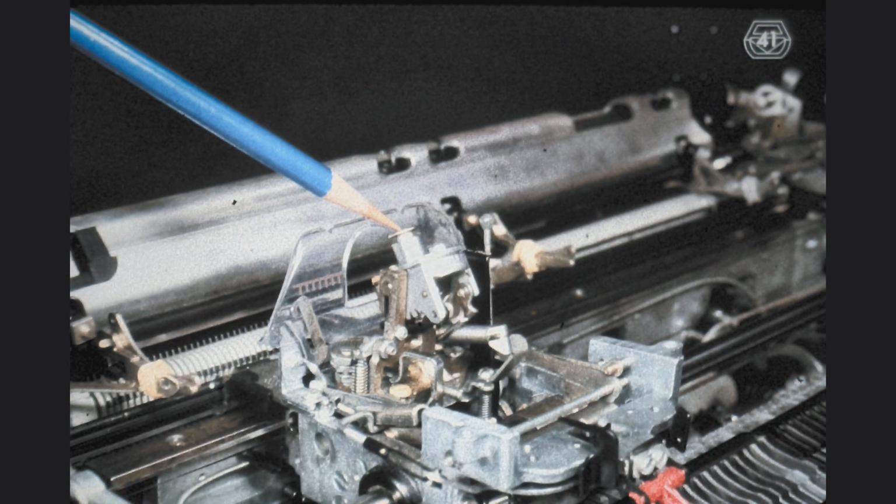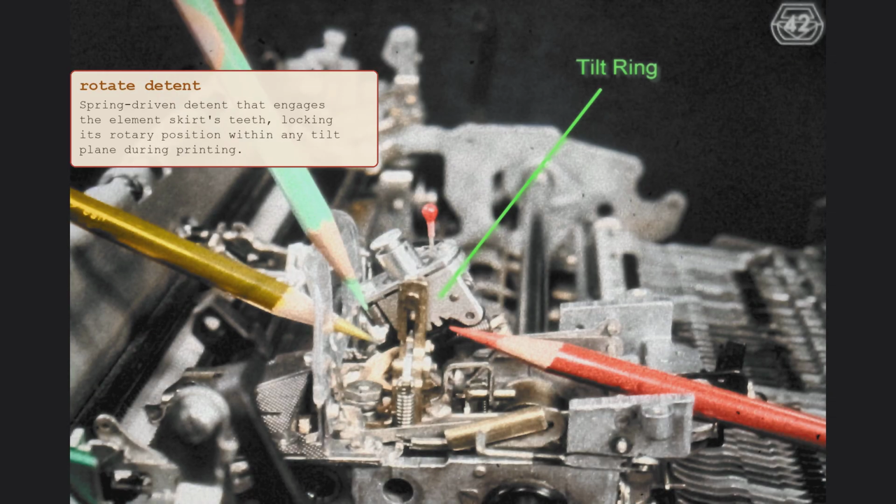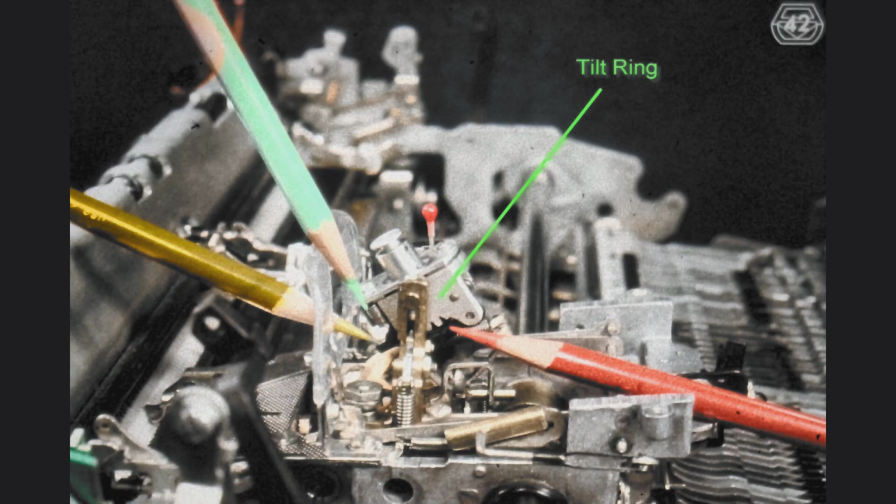Holding the tilt ring in its position during printing with the use of the tilt detent is not yet all there is to locking the element into position. The element is supported by the indicated part, called the upper ball socket. The upper ball socket still has the ability to rotate within any one of the tilt positions into which the tilt ring can be locked. Rather than lock the upper ball socket to prevent it from rotating, the Selectric typewriter locks the element directly by a detent called the rotate detent. When the tilt detent is allowed to operate, it also releases the rotate detent, allowing it to operate.